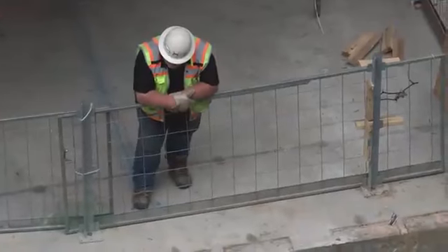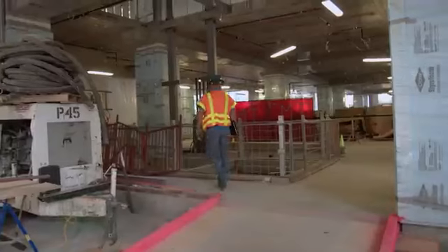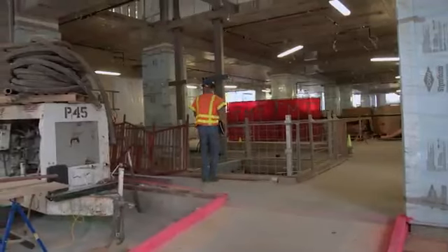As far as building guardrails and safety rails, it just depends on what the construction material is that you're having to work with. But building a wood rail, again, the bottom rail 21 inches up, the top rail at 42 inches, it's not terribly difficult. It does need to withstand the weight of someone leaning on that rail. So it does need to be positively fastened. It needs to withstand side pressure of 200 pounds, so it does actually need to be built correctly, but very simple to do. And there's also products available on the open market that you can buy that are an easy bolt together system that will do the same thing.